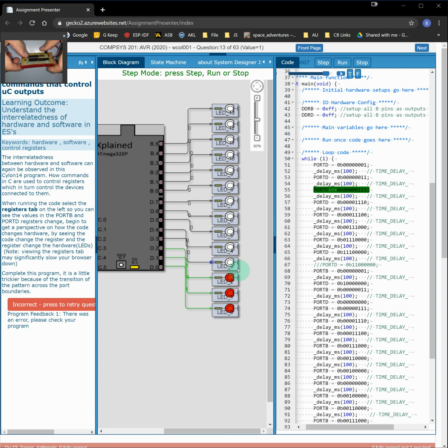So if I don't turn off the previous LED, what I'll end up getting is all of the LEDs turning on together, just in a sequence. And I want to avoid that. So as I keep stepping down here, you'll see that this becomes exceedingly clear when we get to the next line of code after this. Now at the moment I've got this line of code on line 67 in the simulator commented out. And so I want to show you what happens if you forget about it. What happens next is you turn on the next LED and you've got 4 LEDs on.